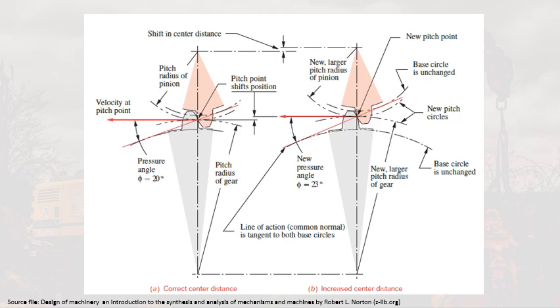There will be some range of center to center distance over which we can achieve a mesh between the gears. There will also be an ideal center distance that gives the nominal pitch diameters for which the gears were designed. However, limitations of manufacturing processes give a low probability that we will exactly achieve this ideal center distance in every case. More likely, there will be some error in the center distance, even if it is small.